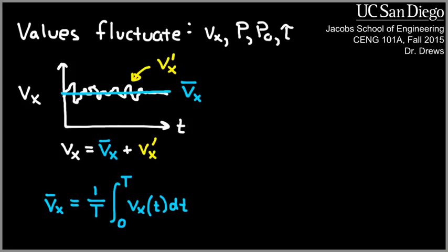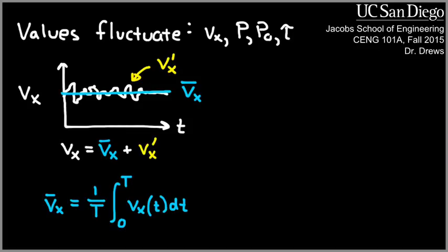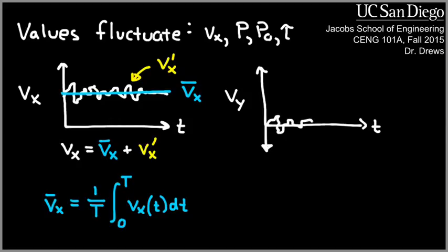That's in the x direction. In the system that we showed here, notice that the velocity profile is only going in the x direction. So if I wanted to look at the y component of the velocity as a function of time, here's time, here's v sub y this time. Now I have to include a little bit of a negative line because here the average velocity in the y direction is still 0, but there's a fluctuating component. And so this component is vy prime.